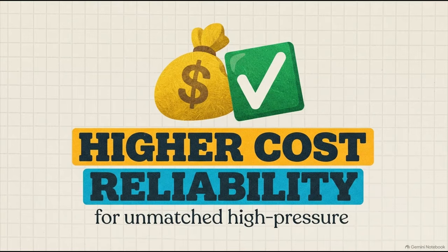Look, because of these insanely strict manufacturing rules, the mandatory destructive testing, and that minimum wall thickness guarantee, yeah, ASTM A213 is definitely going to cost you more upfront than a general service standard, but honestly, it's a completely necessary investment. You aren't just paying for a piece of steel here. You are paying for unmatched high-pressure reliability. You're buying the peace of mind that your tube won't catastrophically explode inside a 600-degree boiler.